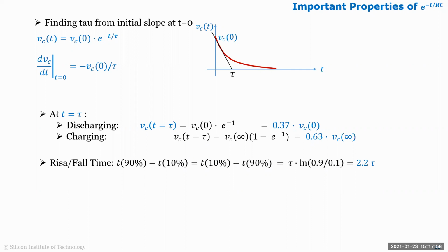So somebody tells you, okay, the rise time is 20 nanosecond. What do you think the RC is? Then you know the rise time they're talking about is 10 to 90%. Sometimes they might define it as 20 to 80, right? You've seen those .lib files where they say 20 to 80. So you have to be careful. So maybe you should do a calculation for 20 to 80 and have that in your toolbox.